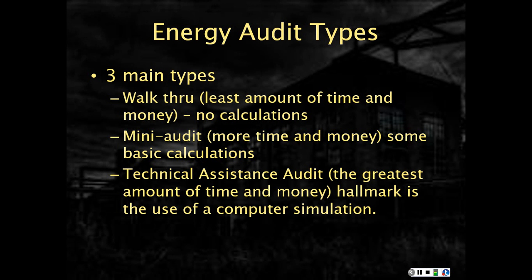Now, once we have that, we can start using the computer simulation to do what-ifs. What if I add a higher efficiency furnace? What if I add a higher efficiency rooftop unit? What if I add insulation to a roof? What if I do combinations of things? How does one energy conservation measure impact another? A computer simulation allows that.